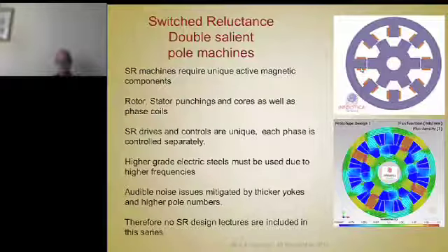So the frequency of switching, or the commutation frequency, or the dB/dt frequency, is different in the stator yoke, the stator teeth, the rotor teeth and the rotor yoke. It's not the same in any of those. So in calculating the losses, you have to solve for the flux density in each one of those four cross-sectional areas, and then use whatever frequency it is to calculate the losses.